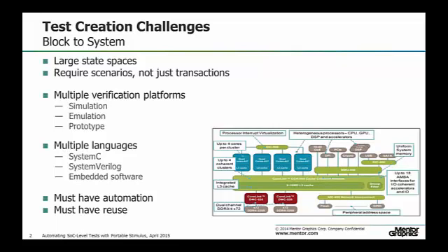The previous speakers have already touched upon it: when you get this kind of system with all the concurrency, the total state space becomes simply too great. There's too many things going on at the same time. It's really impossible to just try and generate all types of transactions to cover all the different scenarios that you're interested in. You need to do a more top-down approach, start to think about which are the scenarios that are interesting, not just the transactions or sequences of transactions.